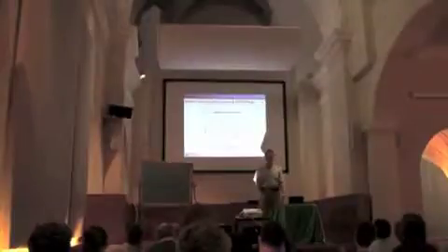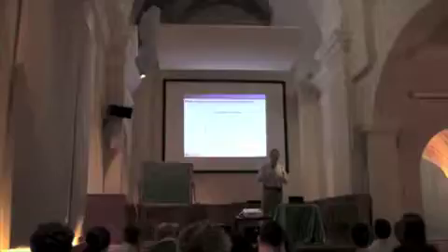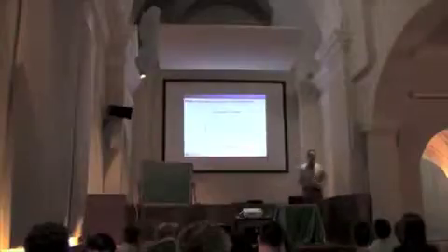So it's the combination of just rocking on the foundation. That's the rigid body motion because of the flexibility of the soil. We usually neglect that. There's the shear behavior that we talked about yesterday, and then there's the bending behavior, which usually we don't think dominates until you get above about 20 stories.